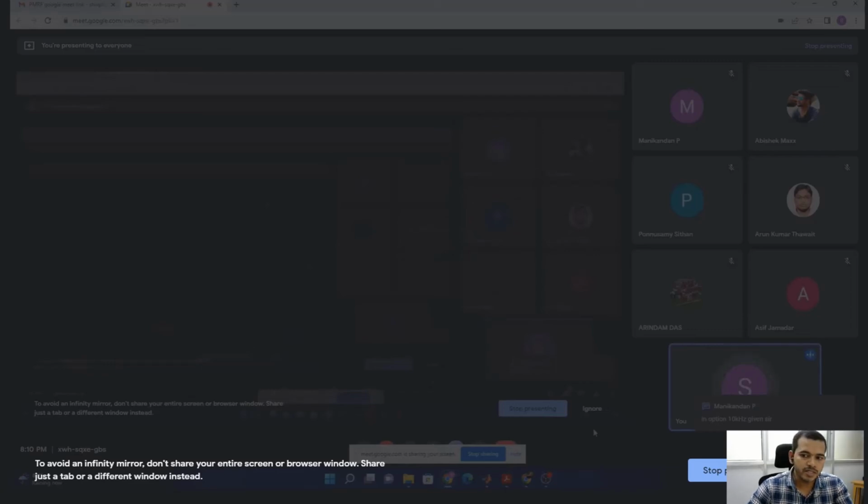No, the standard is 1 by 3, actually given in the standard rules. That's why I have taken 1 by 3 only. Don't take 10 kilohertz for the boost converter and buck-boost converter. For a buck converter there is no right half plane zero, so you can take 10 kilohertz or 50 kilohertz. But for the boost converter, the right half plane zero is present. That's why you take 1 by 3 of the right half plane zero frequency.